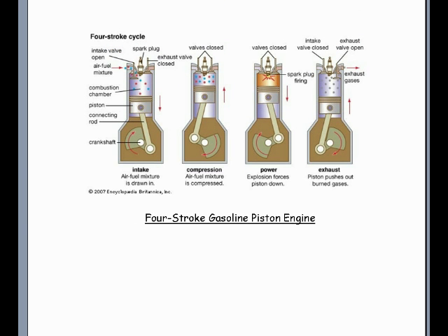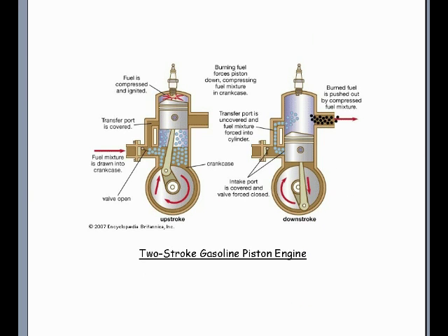The 4-stroke piston engine will go through 2 revolutions of the crankshaft for 1 power stroke, whereas the 2-stroke piston engine will have 1 power stroke per 1 revolution of the crankshaft. With the 2-stroke piston engine, the gasoline must be pre-mixed with 2-stroke oil at the ratio of 1 US gallon per 4 ounces of 2-stroke oil.